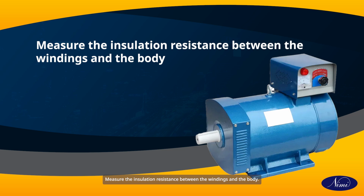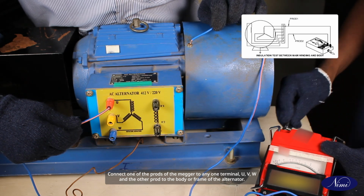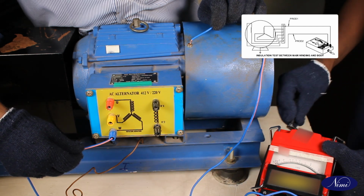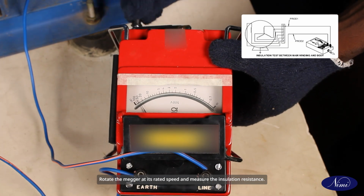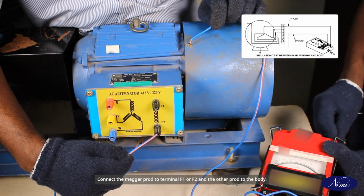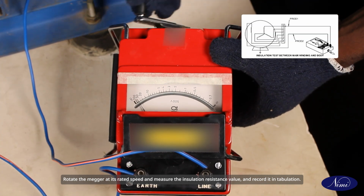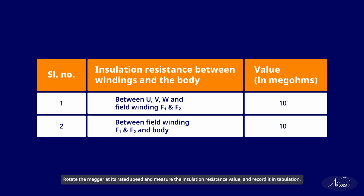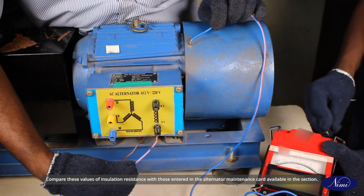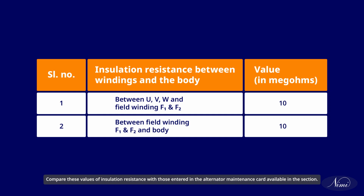Measure the insulation resistance between the windings and the body. Connect one of the prods of the megger to any one terminal U, V, W and the other prod to the body or frame of the alternator. Rotate the megger at its rated speed and measure the insulation resistance. Connect the megger prod to terminal F1 or F2 and the other prod to the body. Rotate the megger at its rated speed and measure the insulation resistance value and record it in tabulation. The measured insulation value should not be less than 1 mega ohm. Compare these values of insulation resistance with those entered in the alternator maintenance card available in the section.